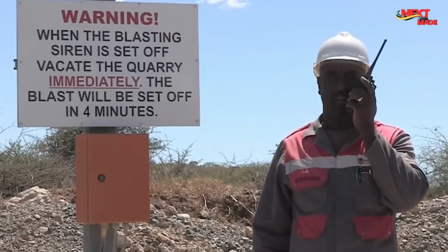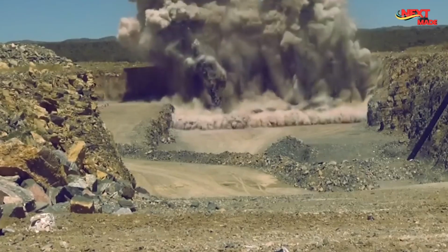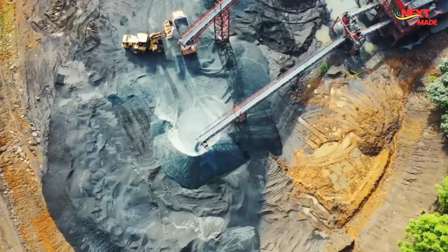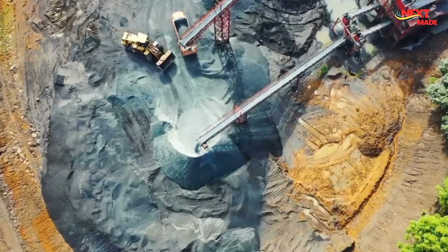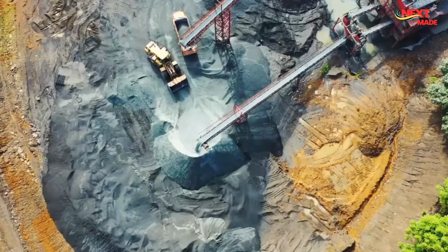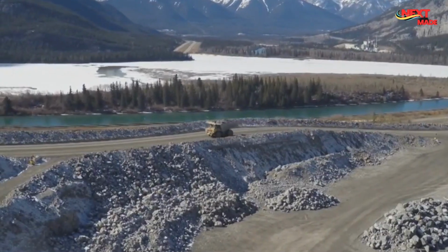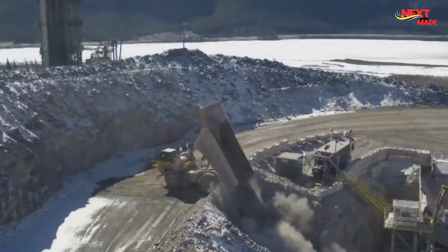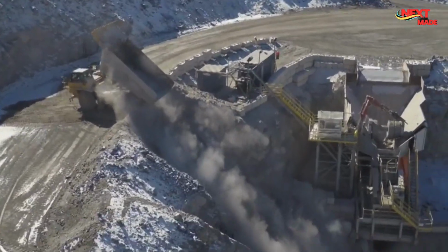It was named by its inventor as such because its color resembled the stone quarried on the Isle of Portland in Dorset, England. The primary raw materials used in cement production are limestone and clay. They are typically obtained from quarries by blasting or using heavy machinery to extract them from the Earth's crust. The extracted materials are transported to the crushing plant where they are crushed into smaller pieces. The crushed limestone and clay are then mixed in appropriate proportions to form a raw meal.